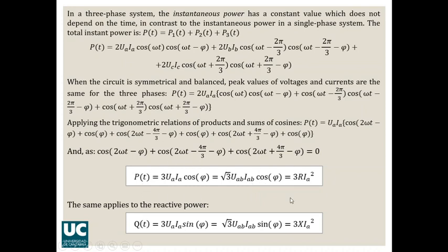All these expressions are also equivalent to 3 times the resistance multiplied by the square of the line current. So depending on if we have voltages and currents, or we have impedances and then we have the real and imaginary part of the impedance, the resistance and reactance, depending on the information that we have in the problem, we can use each of these 3 expressions here.